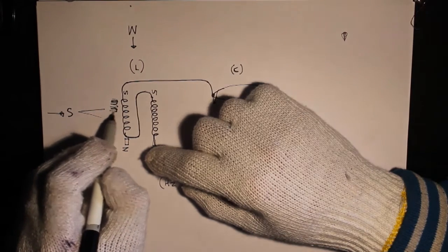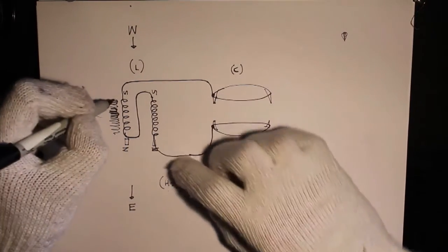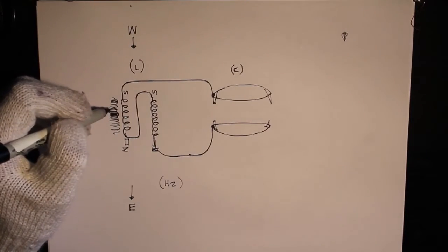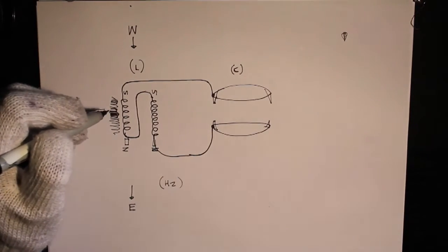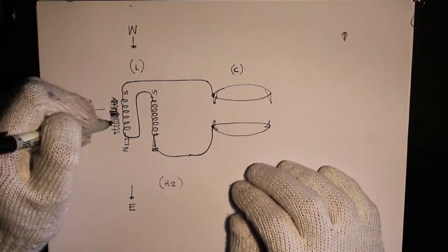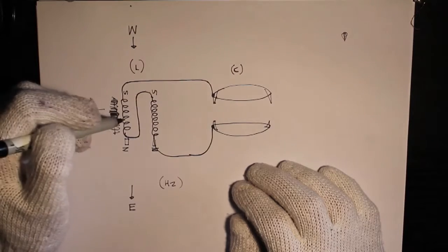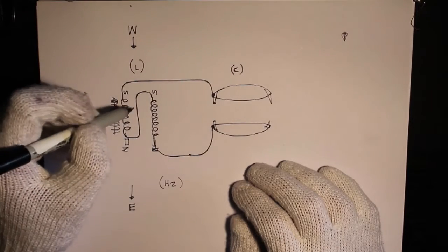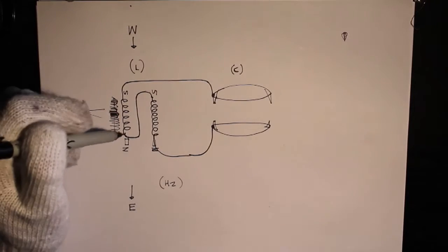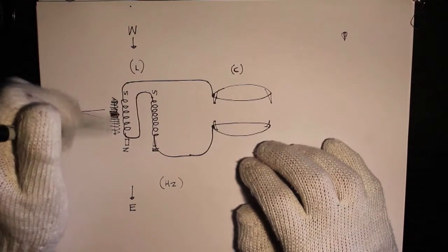Goodness me. There's a lot in the middle, and then they space out. The reason they're wound like this is not for electrical purposes, but because they have to do two functions. You're winding them like that for the energy, but also their inductance value is what alters the tuning of this circuit electrically. So the two systems are always combined, and you must accommodate both.